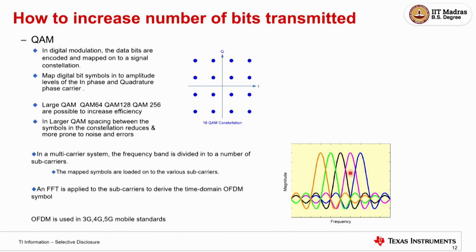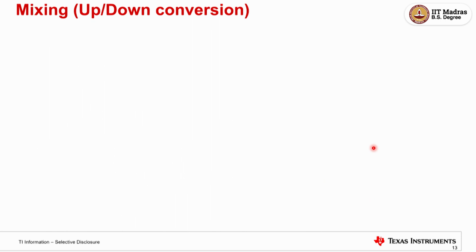I'm not going into the details, but OFDM is an extension of QAM and quadrature modulation with multiple carriers, and it is the standard used in most communication systems now. It helps alleviate some of these problems, like the noise part I was talking about, and improves the immunity in detection. It's more like signal processing in the digital domain. Just to give a summary.